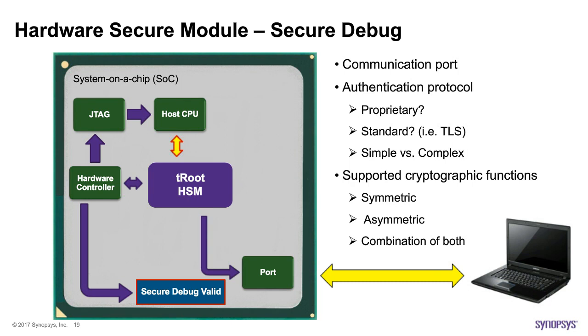authentication scheme. Today, most vendors, like secure JTAG enabling feature, for example, use a simple approach, which is a shared static secret on both sides. The secret is typically burned into the SoC, therefore if the secret is ever revealed, it compromises the chip or, worst case, compromises the family of chips that share the same secret. This implementation has a weak security, but the overall cost is incredibly low.